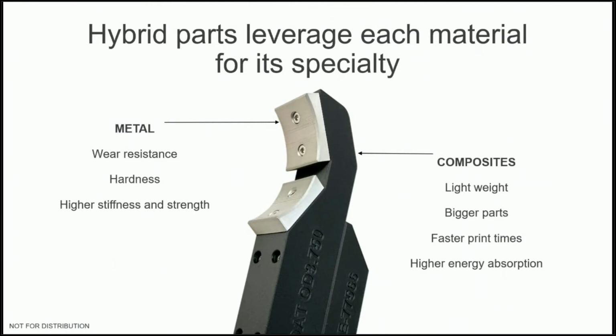Here's a hybrid part, so we're able to utilize composites to lightweight the product, and then we could use metal for wear resistance. In this case, we're using tool steel for the touch pads.